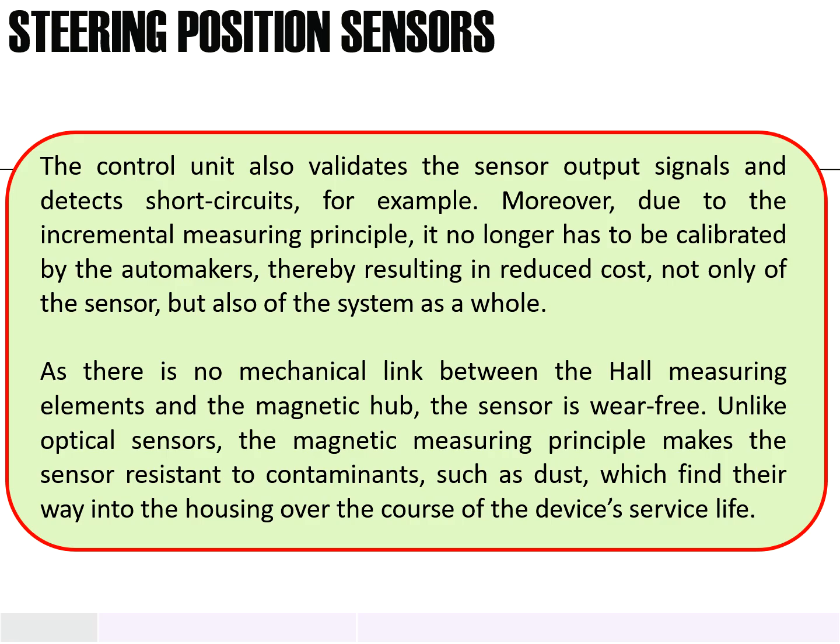When the steering wheel rotates, the magnetic field seen by the Hall elements changes. Two or more Hall elements can be used in this mechanism. The rotary movement generates square wave signals. These signals have a particular phase relationship with respect to each other. The phase difference between the signals provides information about the direction of the rotation.